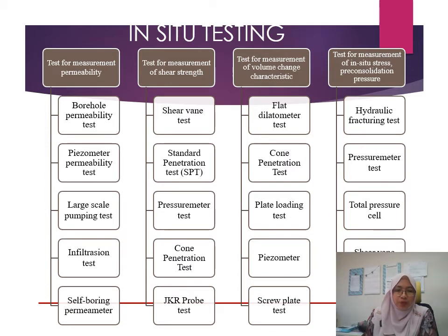For permeability, we can use the borehole permeability test. We can conduct field testing or a pumping test to determine the permeability, as we have learned in basic soil mechanics.